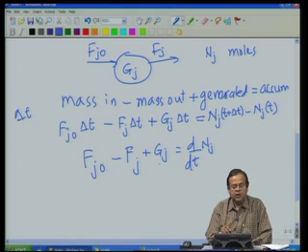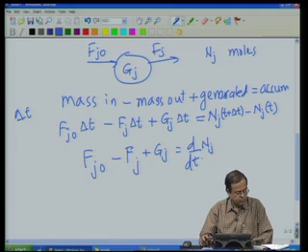Each of these terms has a dimension of rate now. Let us start with the right hand side. The right hand side is the rate of accumulation of species J, dNj/dt, which is the result of what is coming in, Fj0, minus Fj, what is going out, and Gj, the generation rate, into that; that must be the net rate of accumulation.